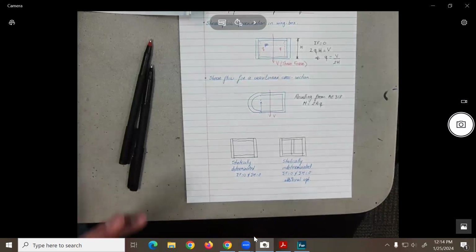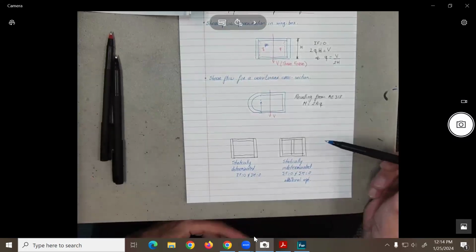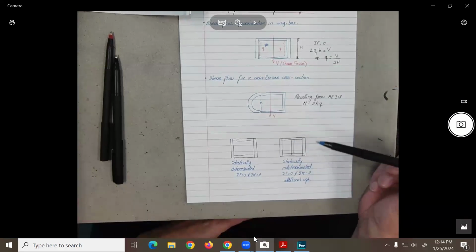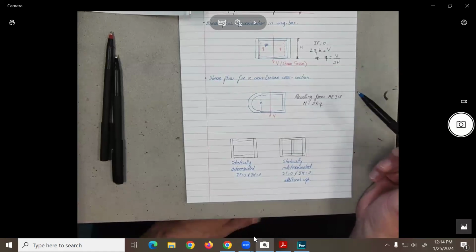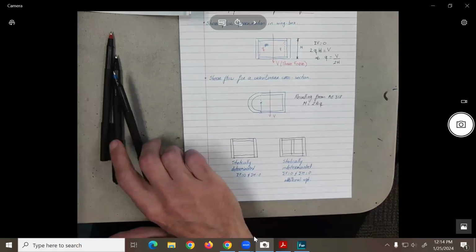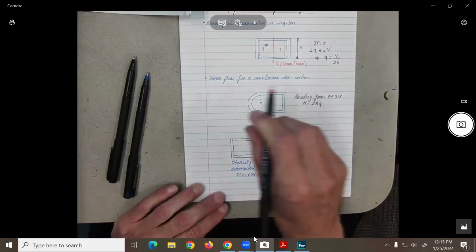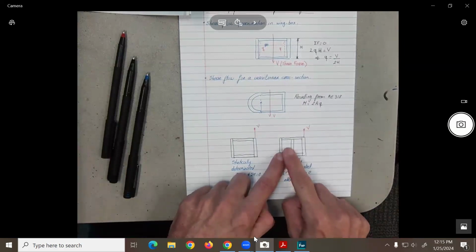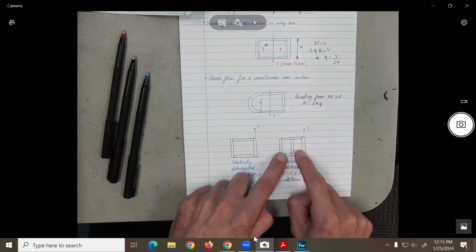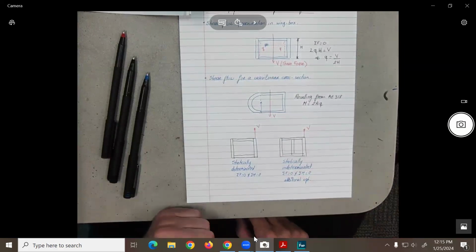In this case, maybe you have done it in Structures 1, or no. What would be the extra condition? Generally, you will find it from geometry. Let's say I put here a force V. What would be that extra condition? The angle of twist of this cell over here should be the same as the angle of twist of this cell. Okay, so that will give us an additional equation, basically by looking at the geometry.